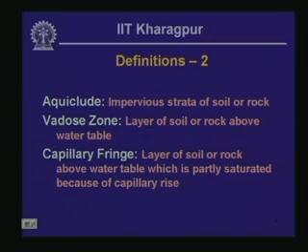If you have very fine grained soils, then that soil can in fact be substantially saturated even if you are considering an element within the capillary fringe. So in such a case, the layer above the water table is also, for all practical purposes, going to be saturated.